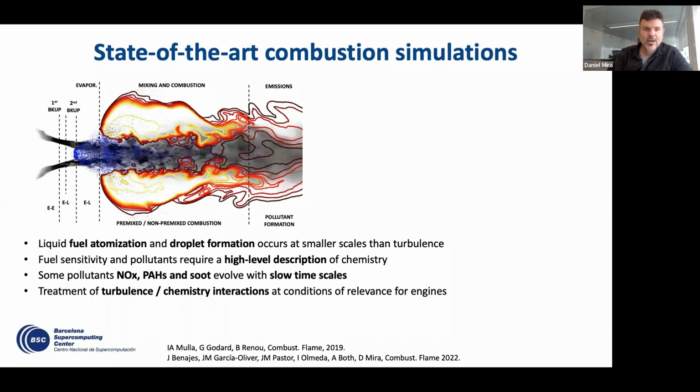Then on the other level, after the fuel and the air come together, we have to describe the ignition and combustion. This is quite important because different fuels will have different burning characteristics, and we have to deal with this. This is why the description of chemistry becomes very relevant. Even more so for pollutant formation, where chemistry is the dominant effect, and we need to accommodate reaction mechanisms with CFD calculations, so we can actually address the realistic problems happening in the engine.